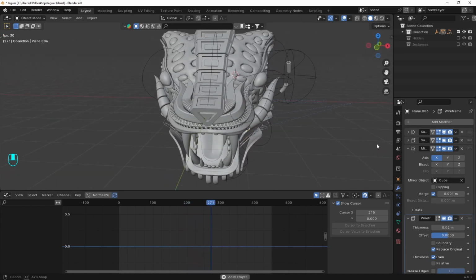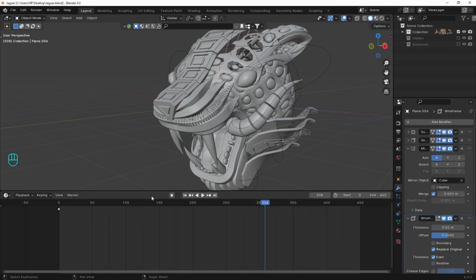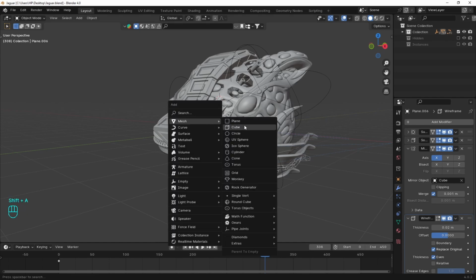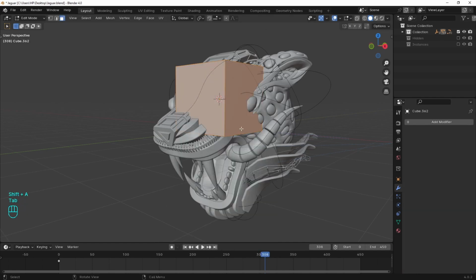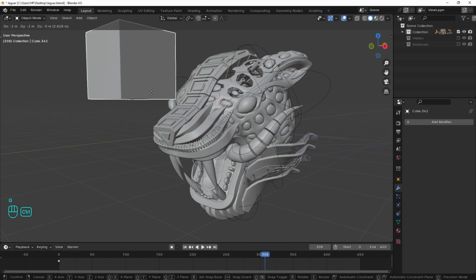The nose loop we have to do with Boolean operations, and this is very bad, especially for animations. On top of that, it will slow down the playback a lot, but I guess it's okay for this thing we're doing. So I'll grab a cube to use as a cutter. We want the origin point at the bottom face, and in edit mode we'll move it up, holding the snapping tool on with Control, which will snap on the grid now.